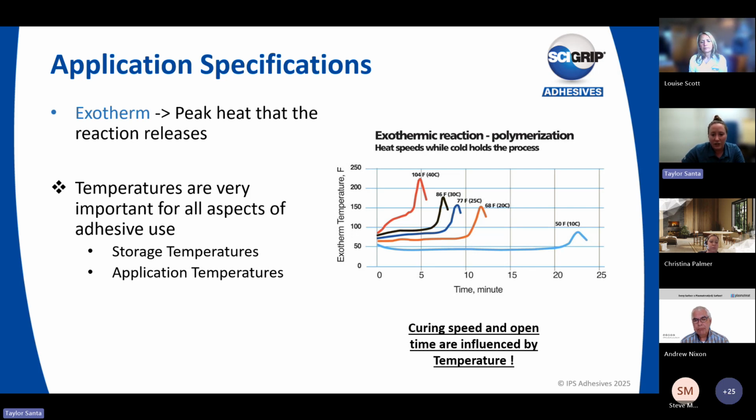The last consideration customers need to keep in mind is the temperature of the environment when the application itself is actually happening. So take Southern Florida. Right now in the summer in August, temperatures are 95 plus, right? With this high external temperature, the adhesives will actually cure much faster. In this graph here, you can see as the temperature rises, the reaction happens faster and faster. The opposite happens obviously in cooler temperatures. The reaction time will actually slow down as the temperature drops.